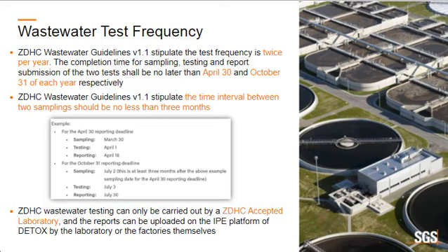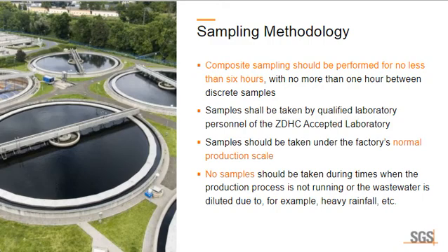And the ZDHC wastewater testing can only be carried out by a ZDHC accepted laboratory, and the laboratory can help the suppliers to upload the wastewater test report to the platform, like the IPE platform for the Detox or the ZDHC Gateway. And for the sampling, the composite sampling should be performed for no less than 6 hours, with no more than 1 hour between the samples.